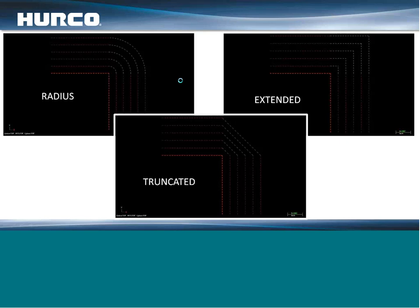So if I go to the graphics here that we created to help explain this, what it wants to know, when there's a change in direction, a 90-degree corner here, is how do you want to handle that surface that you're creating? The first option, which is typically the default, is radius. It's just basically going to offset out this surface, and where it offsets, it's going to connect the two tool paths with the radius. So it's going to round those off, and you end up with a rounded or conical corner.